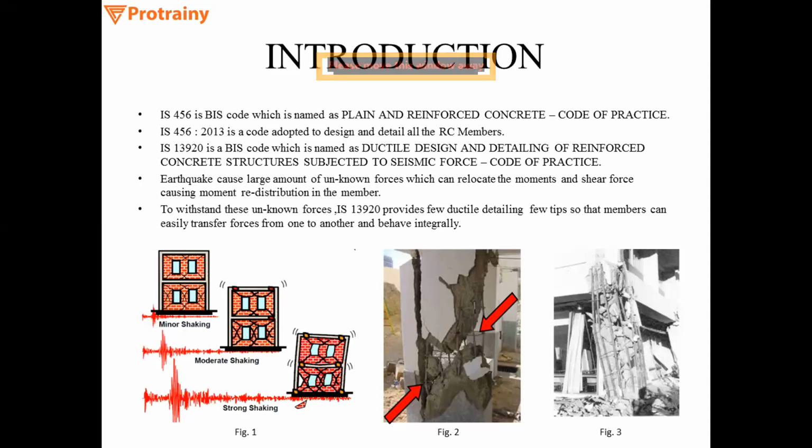In a building, if a column collapses, the structure cannot withstand anymore. So we need to have a better design and better moment capacity of column as compared to beams or other structural members, because load needs to be transferred by the column itself to the foundation level.